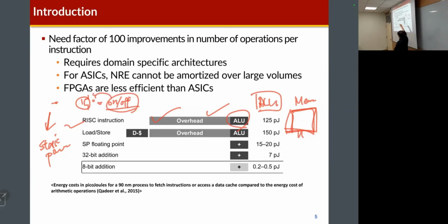So even though the transistor is off, charges pass through the transistor channel. That's why static power is increased recently. Think like this: the memory components occupy a large area, and this memory is turned on, which means the supply voltage is provided to this memory component. So based on the occupied area, this memory will consume actual power. So this is another problem.